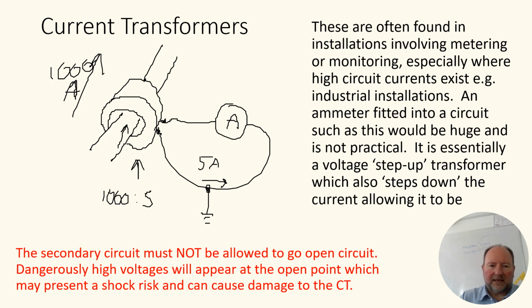But it'll also have the precaution of some sort of switch or shorting link, because the current transformer itself must not be allowed to go open circuit.